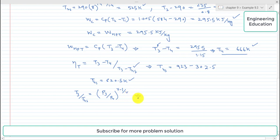So rearranging this expression for P3 by P4 and putting the values, we can write it like this: T3 is 923 Kelvin and T4 is 620.5, power, gamma value is 1.333 over 0.333, because gamma is 1.333, and if we subtract 1 from this value, it will become 0.333. So the value of P3 by P4 comes out 4.9.